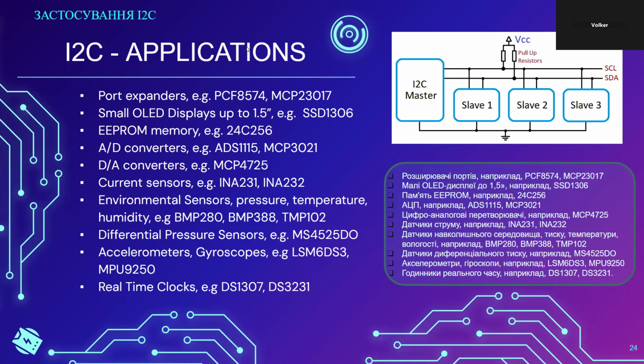GPS modules are traditionally interfaced through a UART. This is historically because GPS modules used to be away from the computing circuitry, because they had to be on the roof. They had to be a significant distance off board to have sky view. Because of that, GPS units traditionally use a UART interface, asynchronous transmission, even though nowadays you buy them as a module and they go onto the same circuit board.